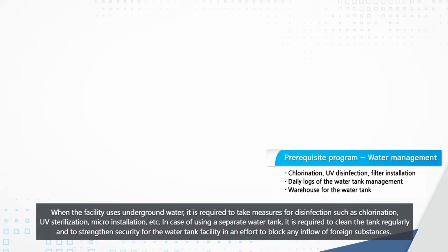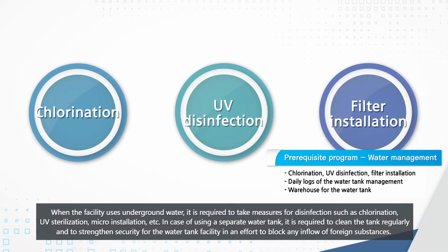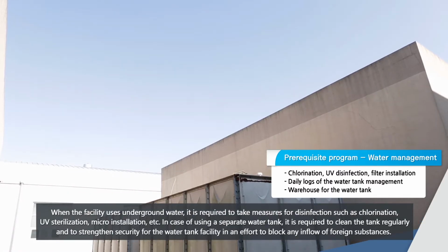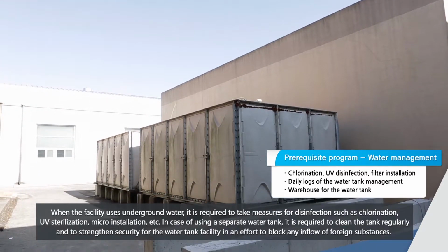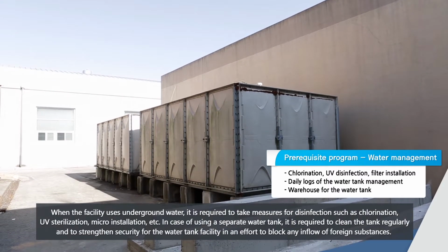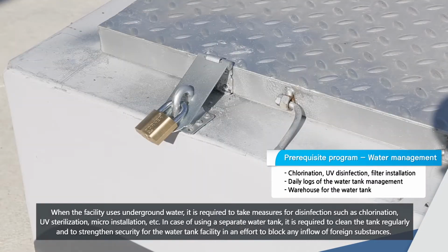When the facility uses underground water, it is required to take measures for disinfection, such as chlorination, UV sterilization, micro-filtration, etc. In case of using a separate water tank, it is required to clean the tank regularly and to strengthen security for the water tank facility in an effort to block any inflow of foreign substances.